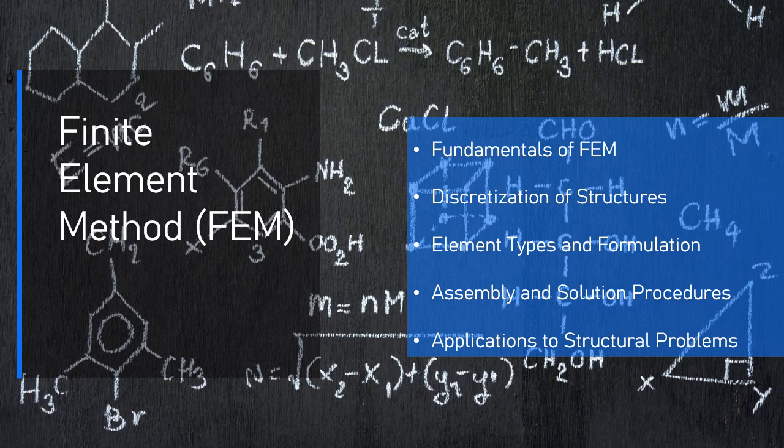2D elements, plane stress, plane strain, shell elements, used for thin structures, such as plates and shells, which experience bending and in-plane forces. Example: quadrilateral or triangular shell elements. 3D elements, solid elements, used for modeling bulkier structures or objects where all three dimensions play a role in the deformation. Example: hexahedral or tetrahedral solid elements.